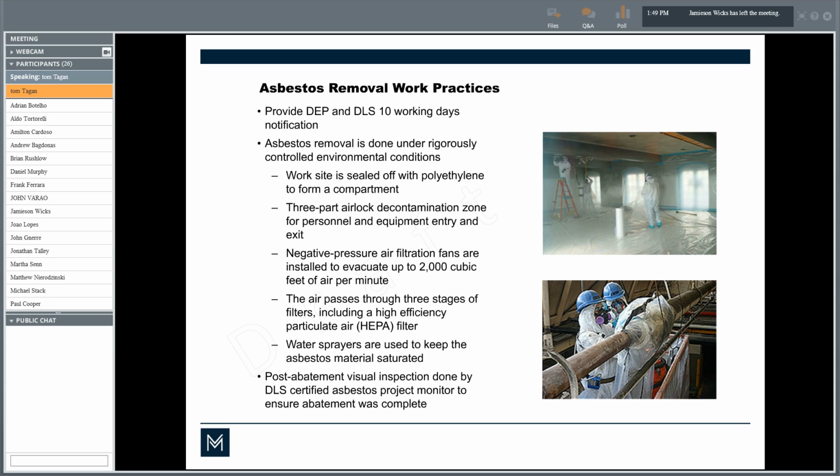And the other thing, too, is you try to keep everything very wet, or not very wet, keep it moist. Because if the material is moist, the asbestos fibers do not go into the air. They drop essentially to the ground, in which case the issues we've been talking about all along from a human health point of view, back to fibers getting into your lungs, are being controlled.